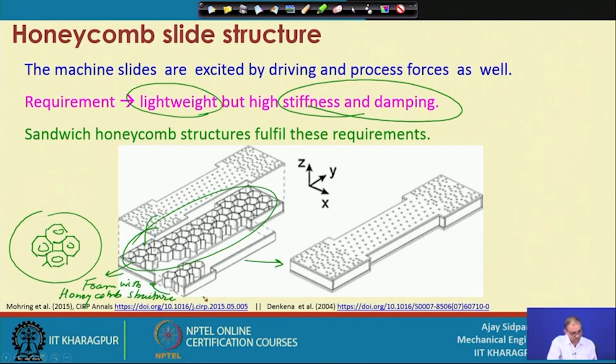That is used for packing material, but right now here we are talking about construction material. So, foam is not the right solution, because we have seen in the slides before, where the materials with respect to Young's modulus were shown against density, that since the density is low, its Young's modulus is also very low. So, it is not the correct way.